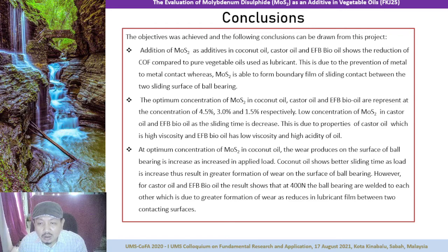Coconut oil showed better sliding time as the load increased, despite the greater formation of wear on the surface of the ball bearing. However, the castor oil and EFB Bio-oil results show that at 400 Newton the ball bearings are welded to each other, which is due to the greater formation of wear and reduction of lubricant film between the two contacting surfaces.